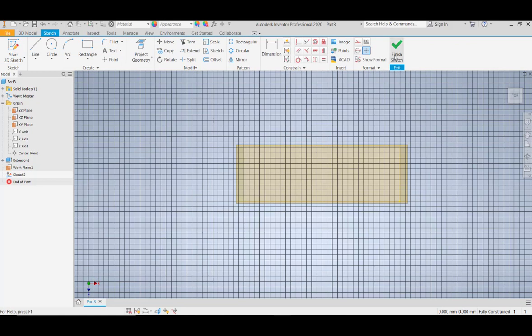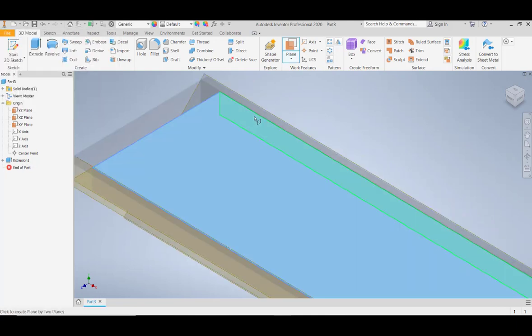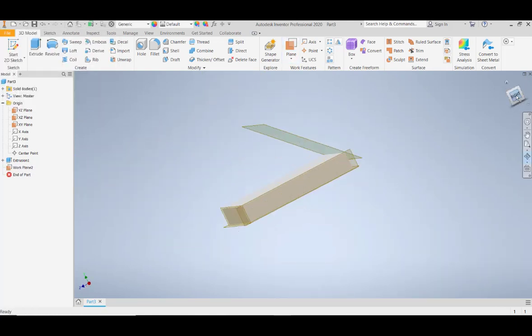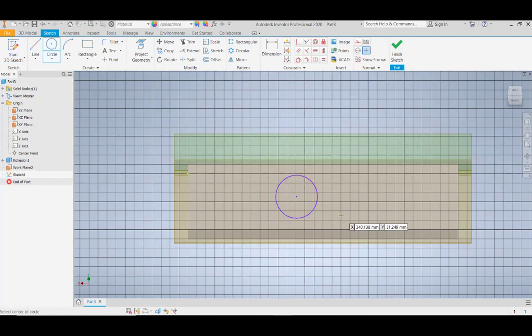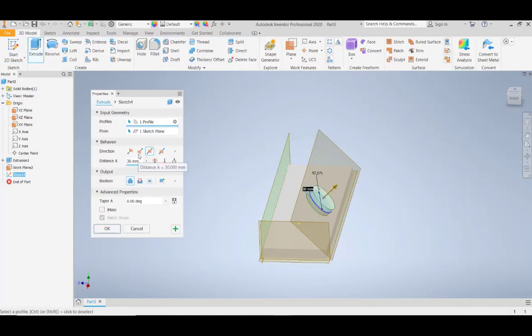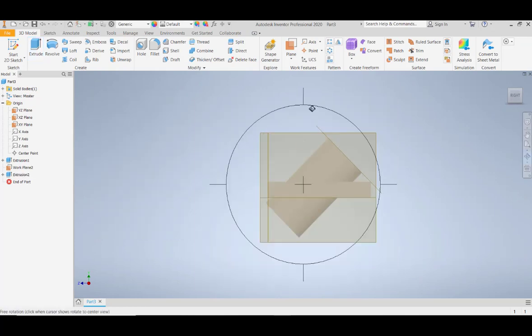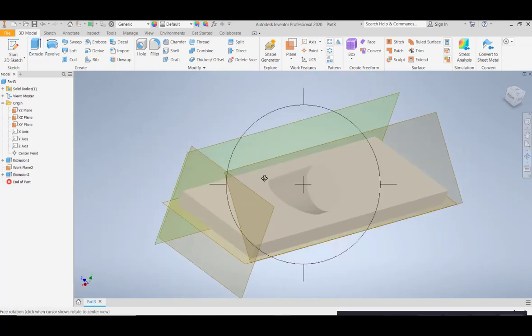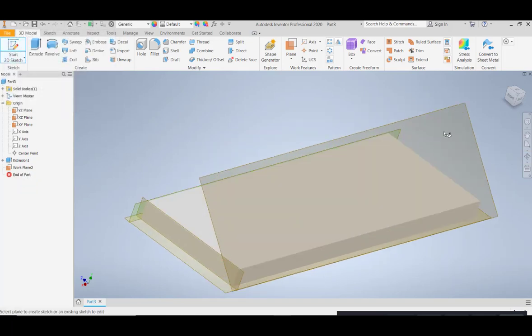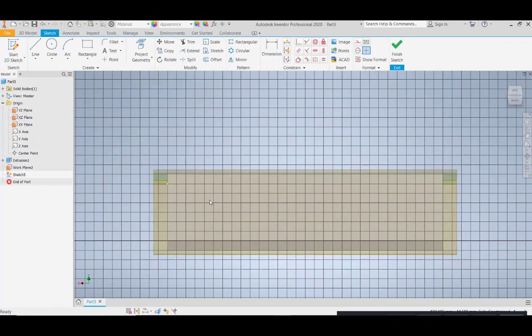When you try to start a sketch in a new Autodesk Inventor part file, you are requested to choose the plane on which you make the sketch. You can choose any plane to generate the base feature based on the design requirements. To add more features, use an existing plane or planar surfaces, or start from scratch.